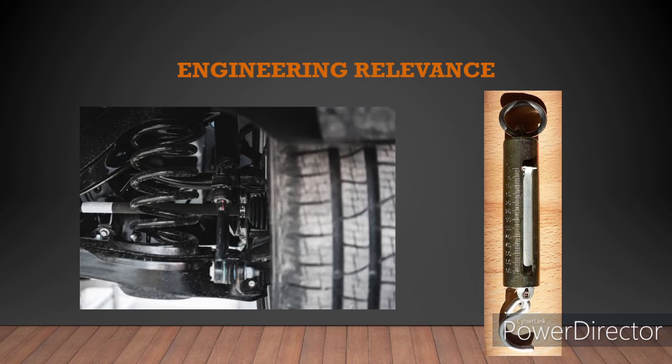It consists of a spring fixed at one end with a hook to attach an object at the other. Because the spring works by Hooke's law, the force needed to extend a spring is proportional to the distance the spring is extended from its rest position.